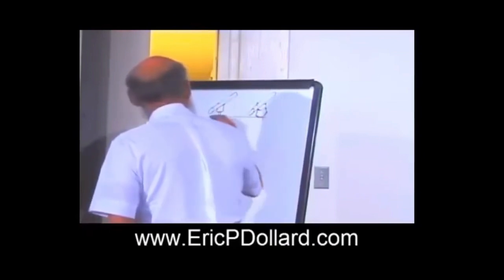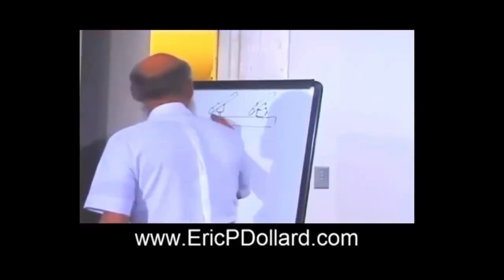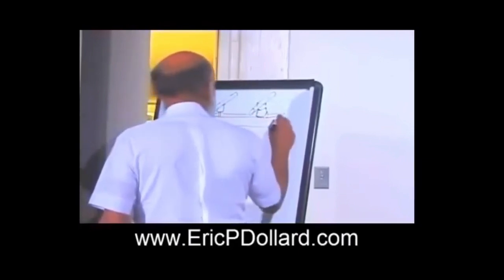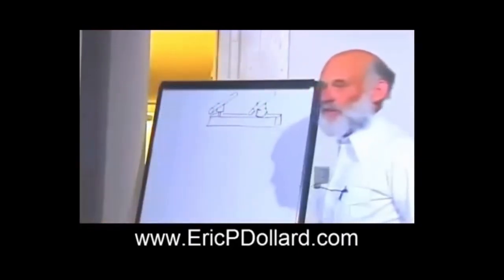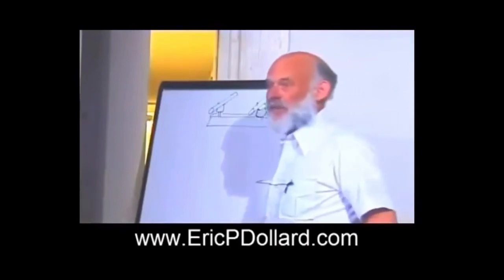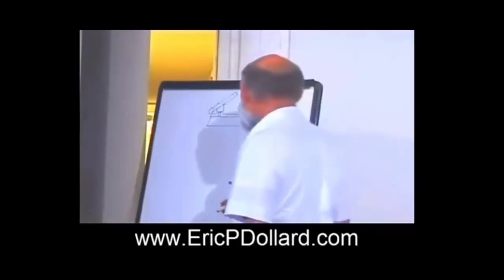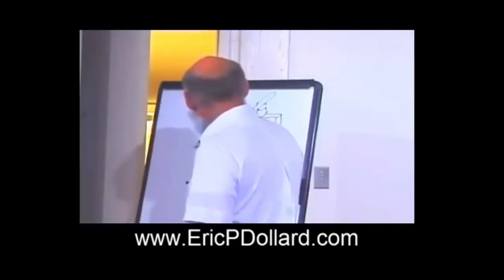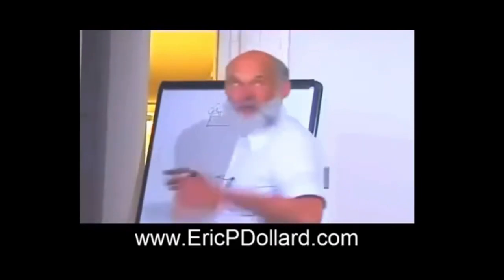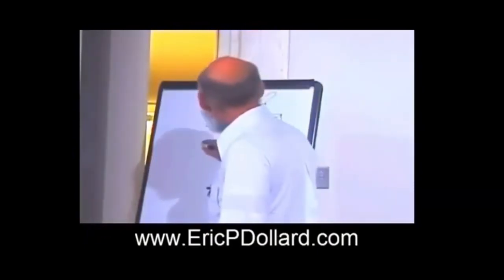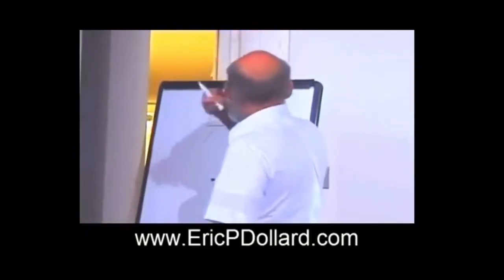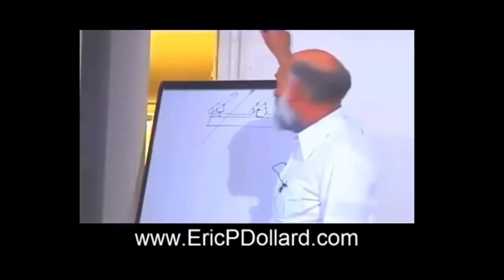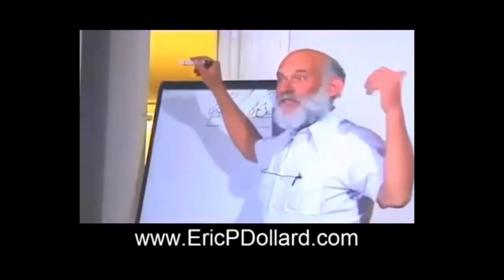How many volts is that? 600. Wow. The feeders are 5,000 amps out of the rectifier. By the time they get here, it's probably more like 500, but if you look at the insulation all burned off, you can see these things have been jammed up to about 2,500 amps. So what I have is a place that produces the electricity. I don't know where the rectifier stations are anymore. There's one back here somewhere between Fulton and Geary, where the juice comes from. It's going down the road between these poles to the buses at the end of the street coming up here.